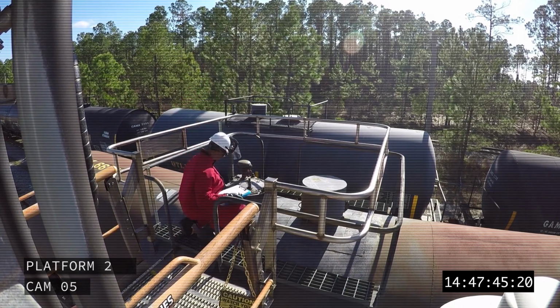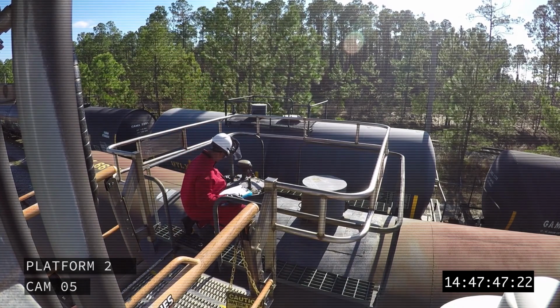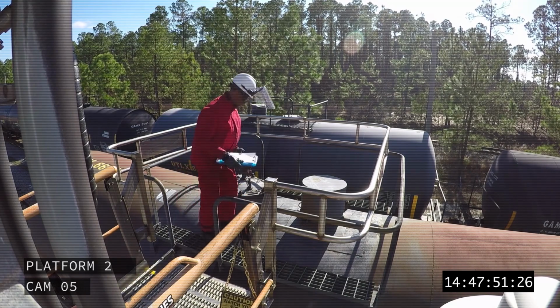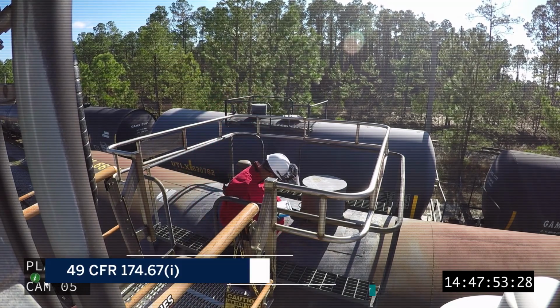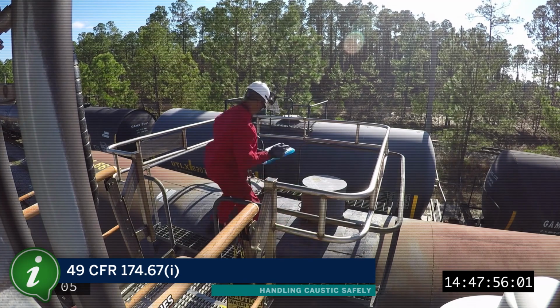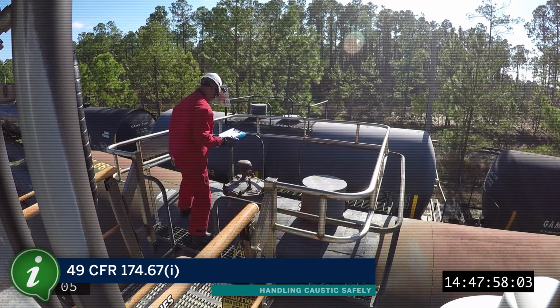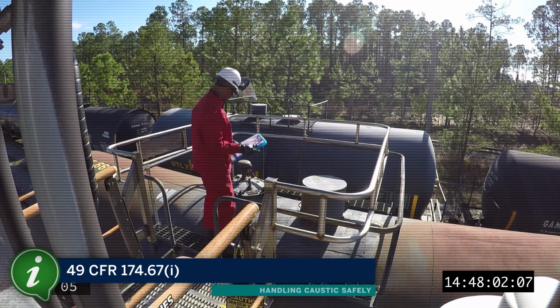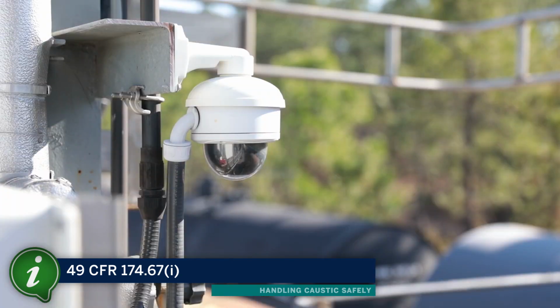For tank cars, although not required by regulation other than for transloading operations, it is strongly recommended to provide continuous monitoring consistent with DOT regulations for transloading. This can be done by either a designated hazmat employee who is physically present or by a remote monitoring and signaling system that is observed by a hazmat employee.